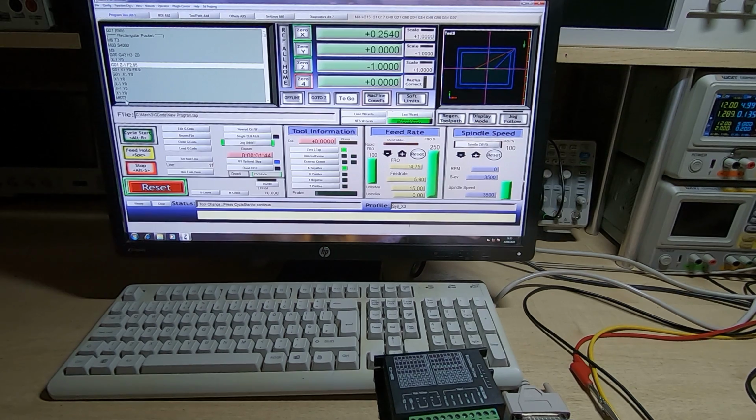So I'll wait now until this next tool change command is executed, and we've got to it now. M6 means tool change macro, T3 is just the tool number that I've told it to request. This is if you're using a tool table, for example. Normally at this point you'd have to find some way to change the tool manually and essentially re-zero it, and that's where it becomes a bit of a pain.